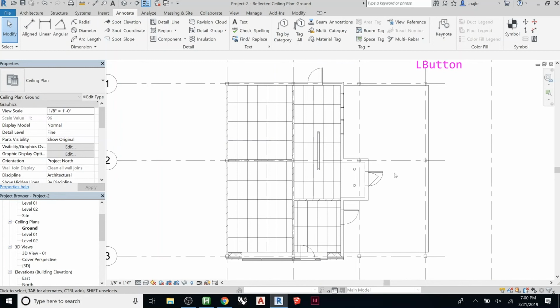So you want your families to be light and simple and just detailed enough to communicate the size, the overall shape, and the proportions, but you don't need more detail in the chair than in your whole building. You can always have that separate with more information. We'll look at that more once we get into creating families on our own.